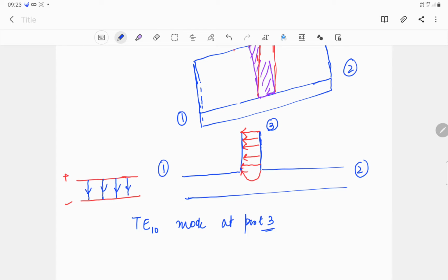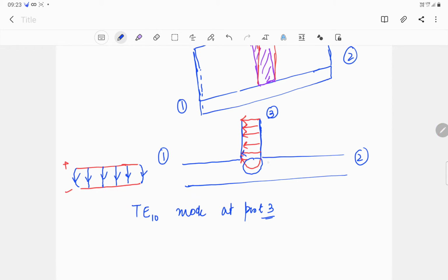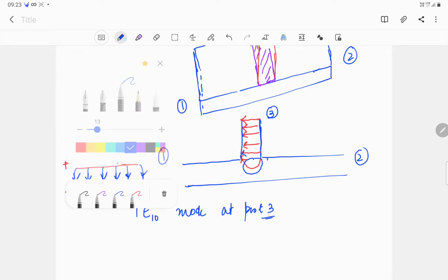Now when we move towards the ends of these plates, these electric lines bend, which is called fringing. Likewise here, in case of an E-plane T junction, fringing occurs. So this line is not a straight line like the other electric field lines, it is bent.